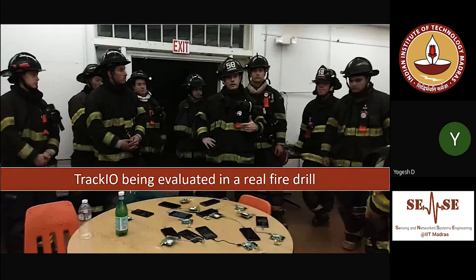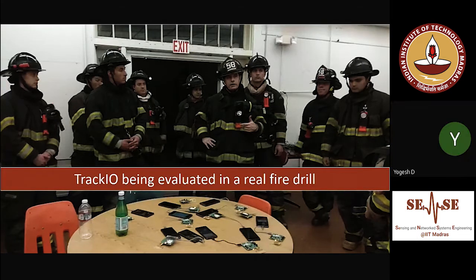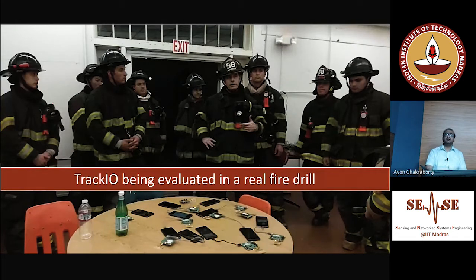Sir, I wanted to ask how robust are ultra wideband signals to heat, to temperature, in the case of fire? It does depend a bit. Primarily, some of the propagation properties at very, very high temperatures might be affected, but the errors that happen can be compensated because the GPS itself is going to have some meter level error. So although the ranging precision might not be in centimeters, it is not going to exceed something like a meter.